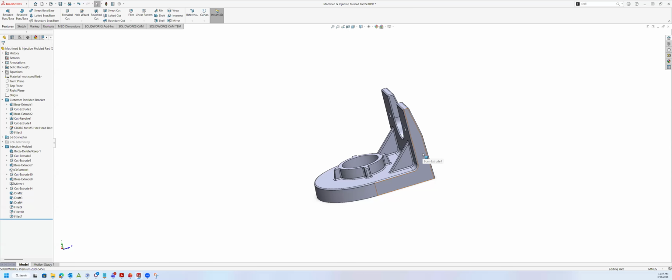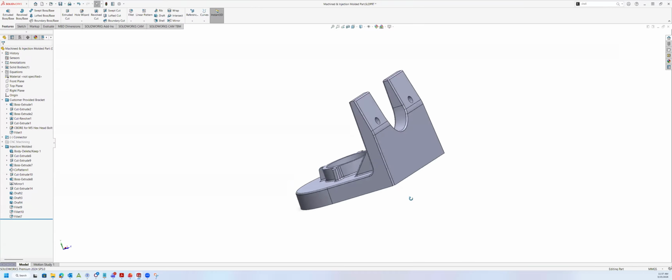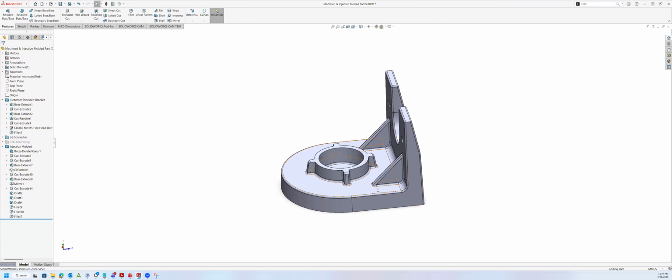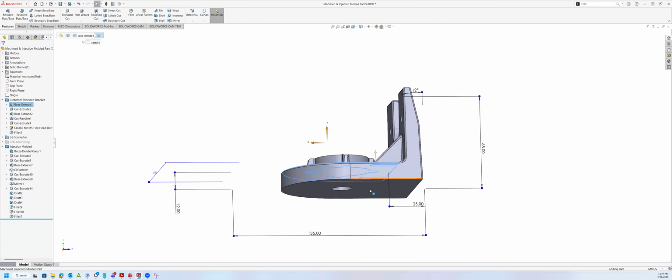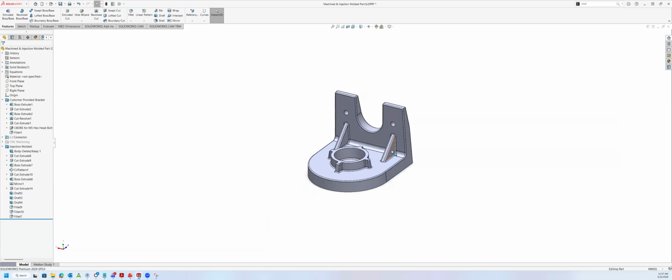Yeah, good question. So for this part itself, we could reduce the overall thickness to match closer to the ribs, or I can increase the rib thickness to match the boss. But my main consideration was to keep this main part at a uniform thickness of about 12 millimeters, and then the support ribs and everything else could be reduced slightly when it comes to thicknesses. Yeah, ribs are not actually supposed to be 1-to-1 to your body thickness. There is a ratio there. It's something like 60%.